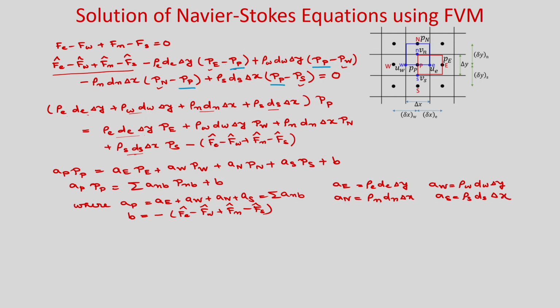Okay. So, in the SIMPLE algorithm, from the known velocity field, first we derive this pressure equation. So, first you solve this pressure equation. In the SIMPLE algorithm you are actually first guessing the pressure field; instead of that you solve this equation and get a better pressure field, so that it converges faster.